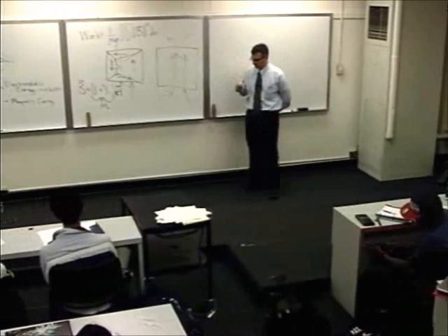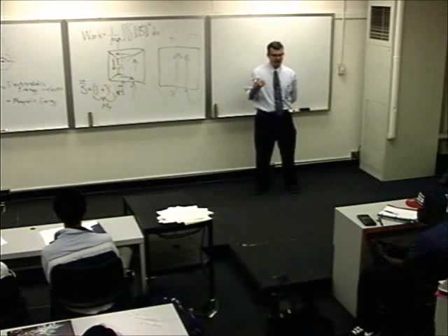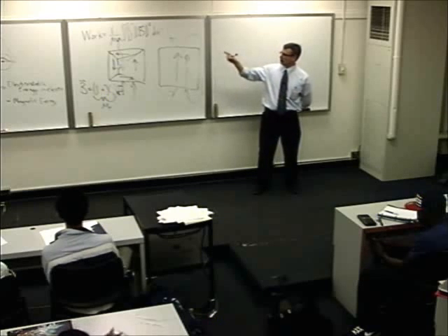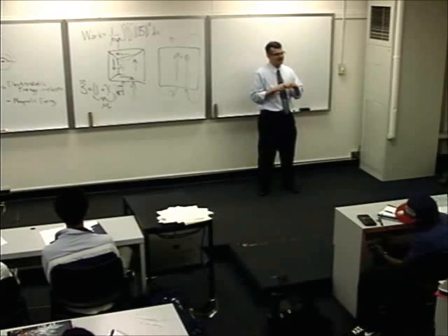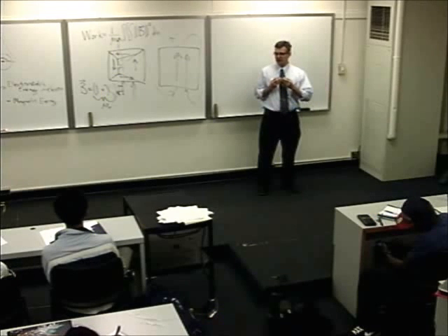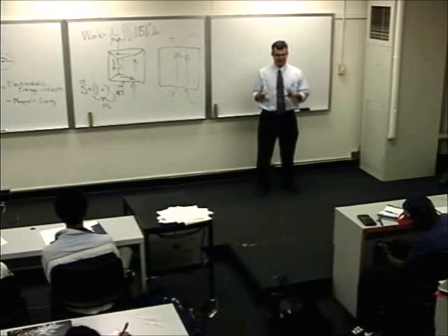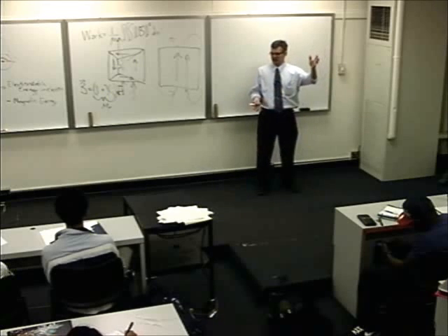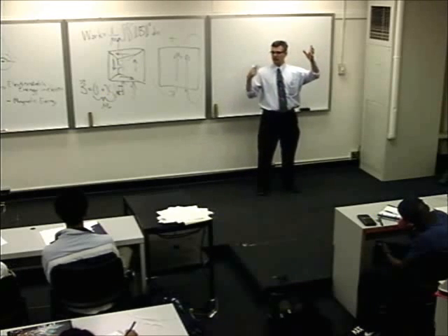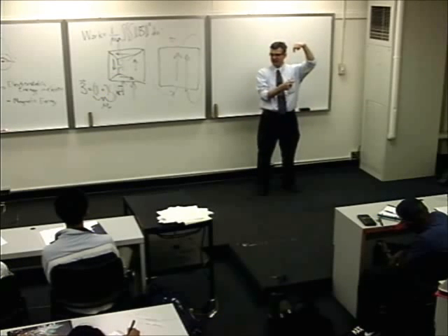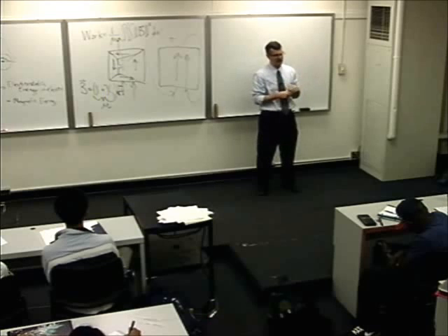Now, when you want a high permeability material, a lot of times what you'll do is you'll take this ferromagnetic material. And the problem with ferromagnetism is that it's usually a metal, right? Metals have conductivity. And so they usually, by Lenz's law, also have eddy currents. So if you put this in the core of a transformer, that's where you want a high permeability material. If you just put solid iron there, it would stink, because you would get lots of magnetic flux through the metal. You could wrap your coils around that and make a good transformer. But you'd also lose a lot in terms of eddy currents.